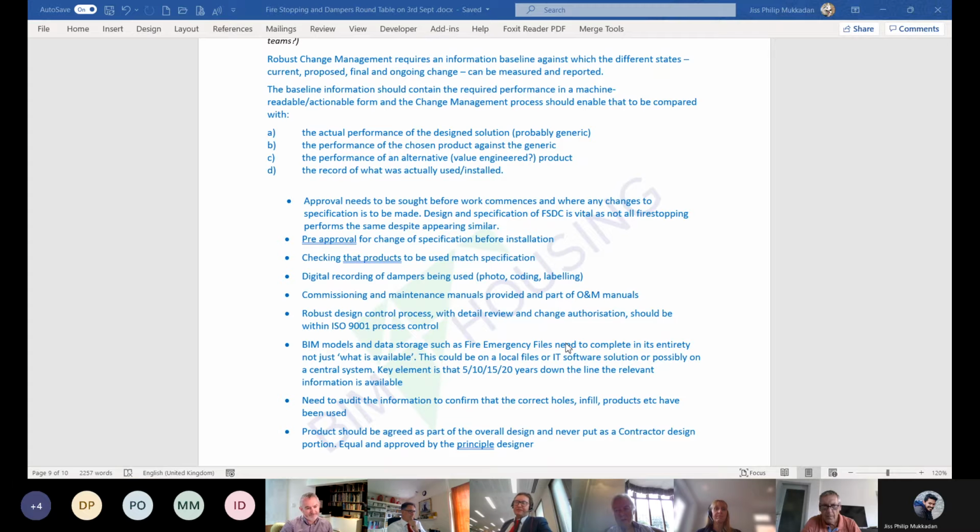Just to add to it, because I'm glad you said that, we're like a tag team here. The classification codes are different. A smoke control damper is different to a low leakage damper, which you might sometimes refer to as an MSFD, but it's a low leakage fire damper. We had this debate recently. The classifications are different. One has an operational classification, one hasn't. And when you look at consultants, and we've had this personally, and Paul's seen it as well, where we're going to a big well-known consultancy, the first question they're asking is, what is a smoke control damper?